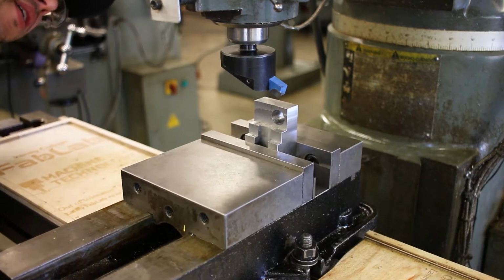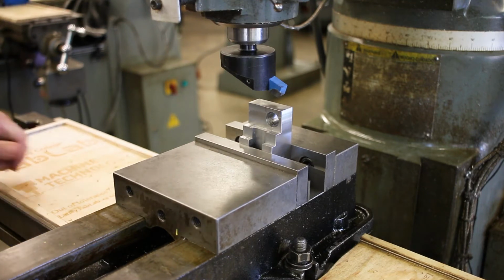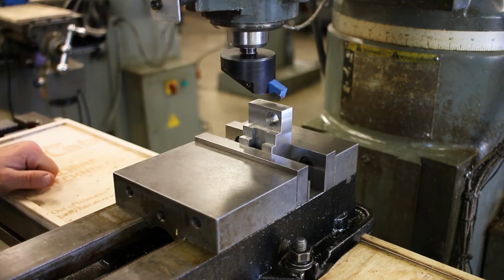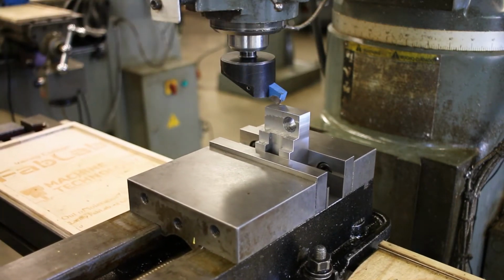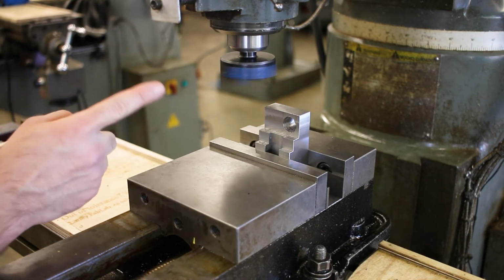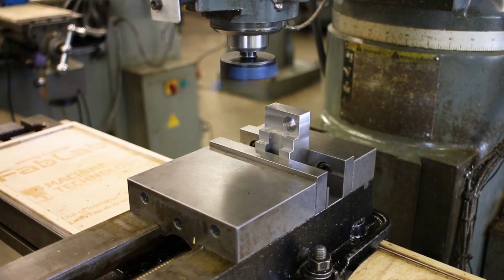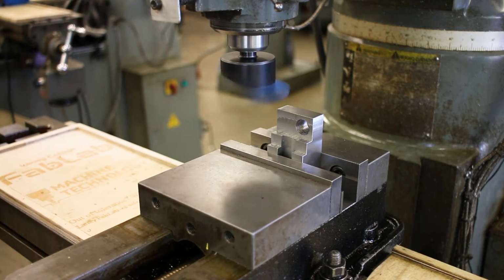I'm going to move the y-axis over a little bit so I can recenter my tool. Okay. Bring the cutting edge close with the quill, about right there. Turn the spindle on. Make sure your quill is locked. Raise the knee slowly till we just make contact. Right there. Okay, zero the knee. Let's give it 5 thousandths and just clean it up.